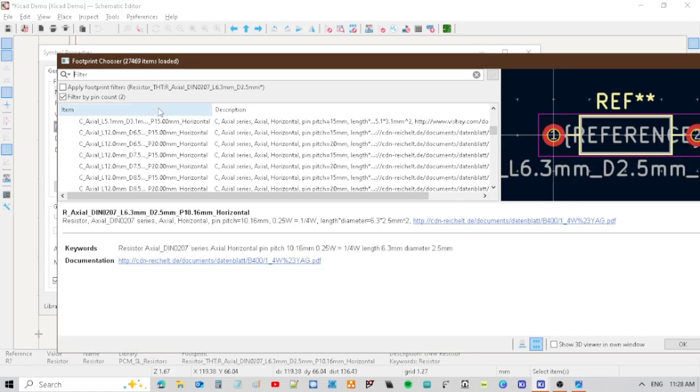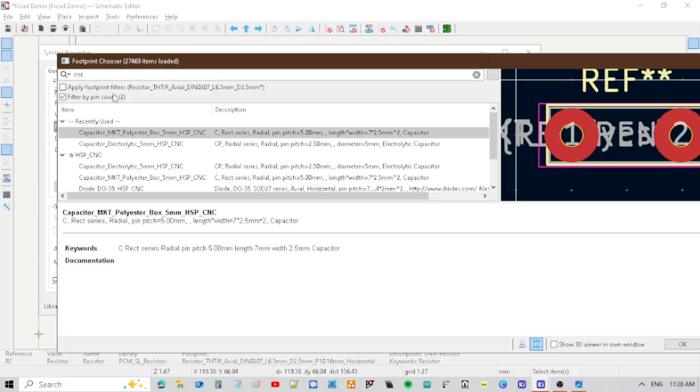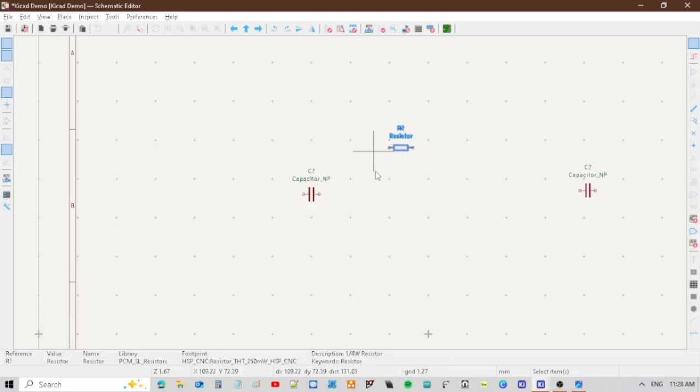Now, the components I've just selected have slightly smaller annular rings and just a little less copper than I like to have when I'm milling. So I have my own, and you'll see when I bring my footprint up that I've made for a resistor. It just has a little bit bigger pad. So I will copy and paste 1, 2, 3, 4 of those.